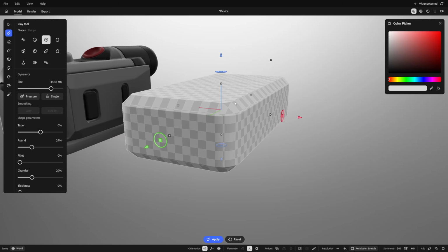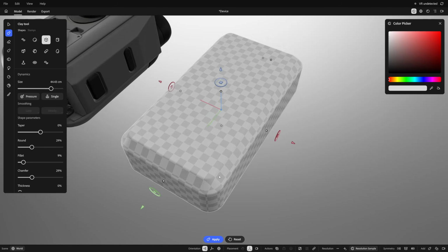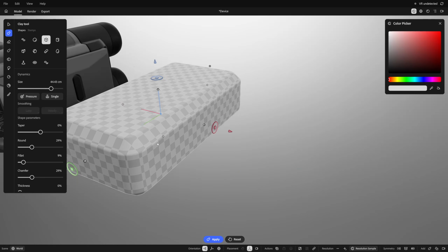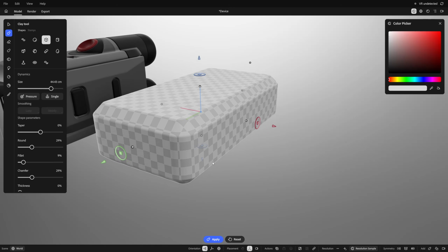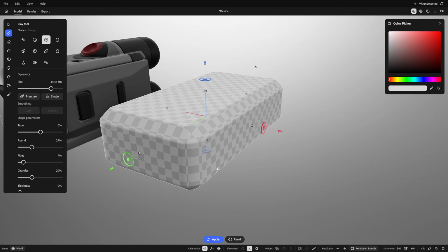But usually if you're doing it non-destructively, you've got to set up 2 different bevel modifiers and use weighted bevels. And if you wanted to bevel the fillet, or excuse me, bevel the chamfer, you would see we've got a slider here for that now in Substance 3D Modeler. So this is way easier to do over here than Blender. It's 3 sliders, not 3 modifiers, and you've got to set them up and tag edges and stuff. So it's really good for design in some respects.